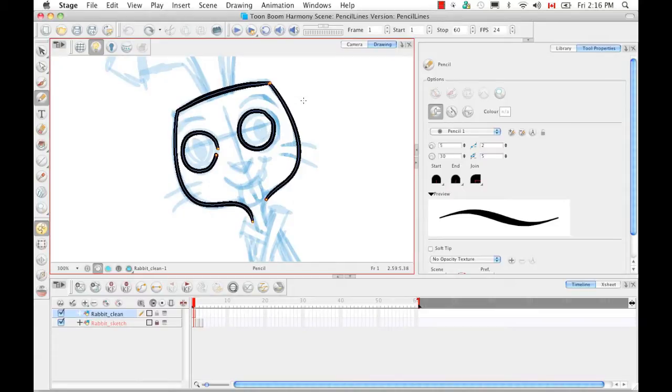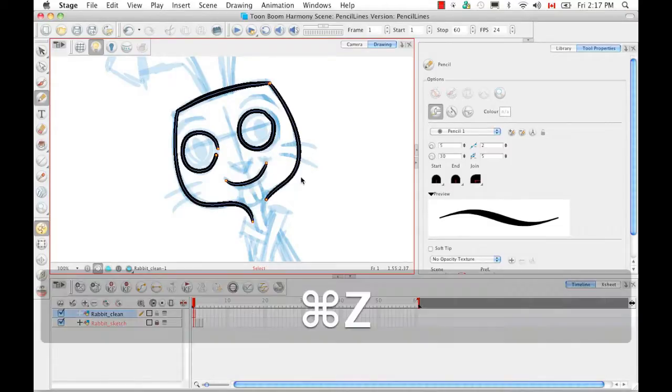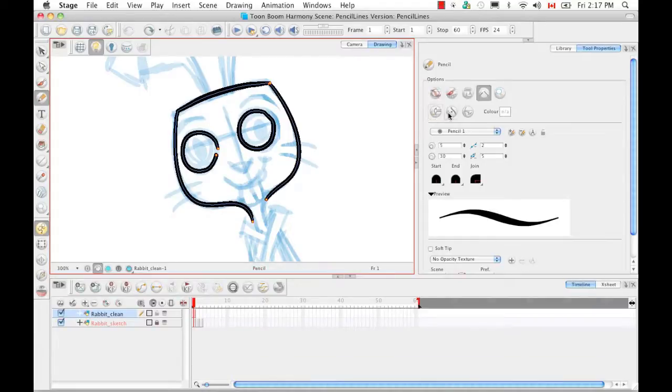When using the line building tool, you have to be careful because you should only use it in instances where you do want to merge and blend your lines. For example, you might not want to merge your lines for the mouth. You might draw one line here and then one line here, but the moment that you draw the teeth, you'll see that the center line for your mouth disappeared. So you could turn that off and try again.